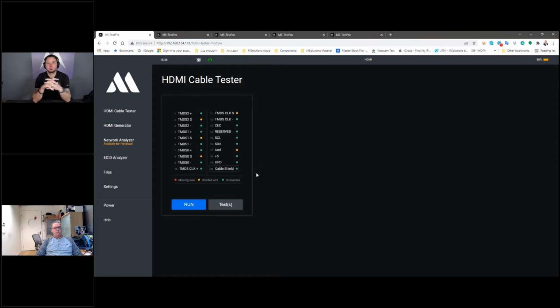We will know that there is this type of implementation. The moment that we move to the compatibility, we will see exactly if this cable can fit what we need. For example, I expect that this type of cable for 4K will not work. It will not be suitable for a long run on a 4K resolution. Why? Because of the shielding, because of the quality of the wiring, we will see problems with it.